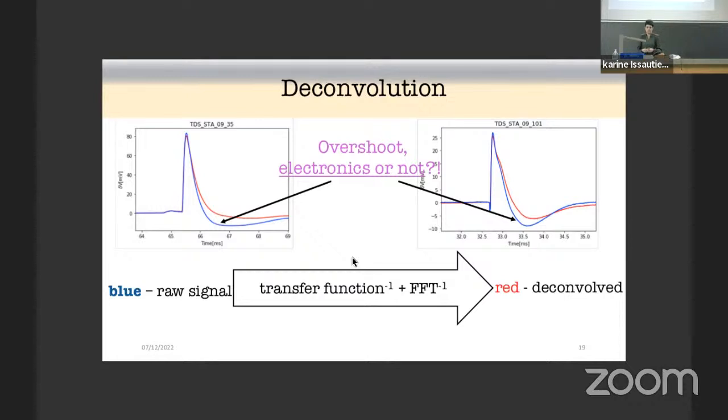That's why this monopole mode is really good for dust observation, because you don't really care where the impact happened, because the capacitance of the spacecraft is large. You assume that the impact happens on the spacecraft. On the spacecraft, yeah. Because it's just a reasonable assumption, according to the big size of the body of the spacecraft.